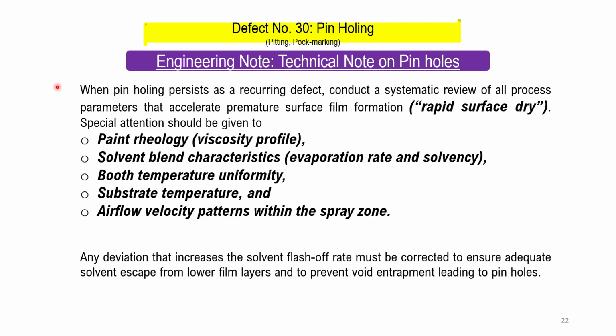When pinholes persist as a recurring defect, conduct a systematic review of all process parameters that accelerate premature surface film formation, that is, rapid surface dry.